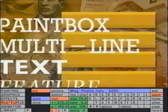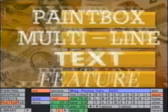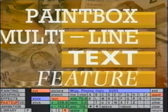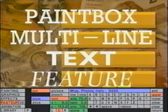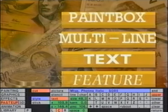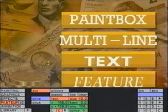The text can be moved by pressing and moving the pen outside the immediate area of the text. At the moment, the text is justified to the left. It can be centered by hitting C, or hitting R justifies it to the right. Here we want it centered. And size down, again being careful to avoid sliding the pen over the text area when changing numbers. Now positioning the whole text with the first line over the top box, further adjustments can be made.